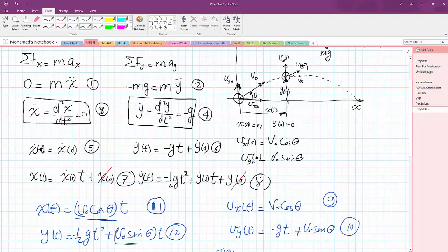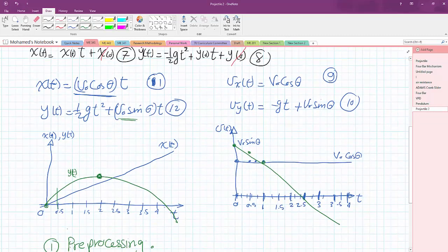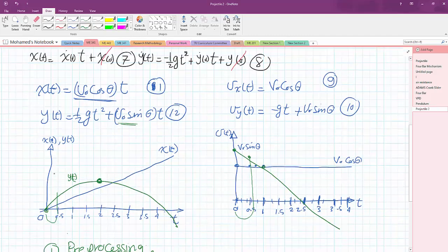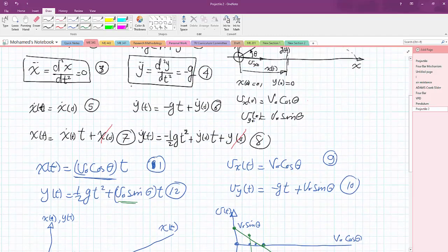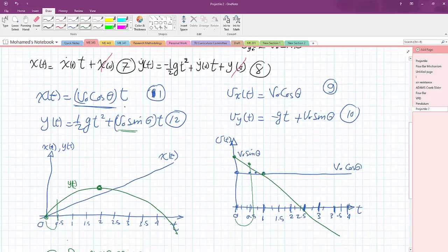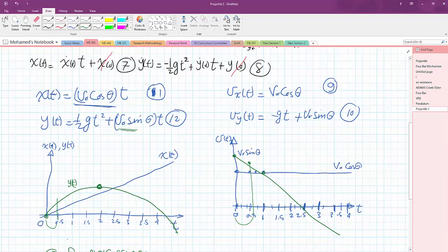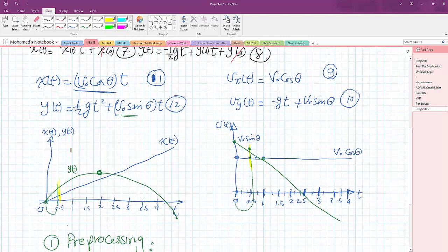But now we would like to know what is going to happen after 0.5 second. So the solver is going to take this time step, and it will use the initial conditions here and solve those differential equations. What do you mean by solving them? It will use the mathematical methods that you studied before, and it will determine the new velocity at this time, the new velocity right here, and the new displacements, and the new forces at the new time. And it will store those values in something like a table.